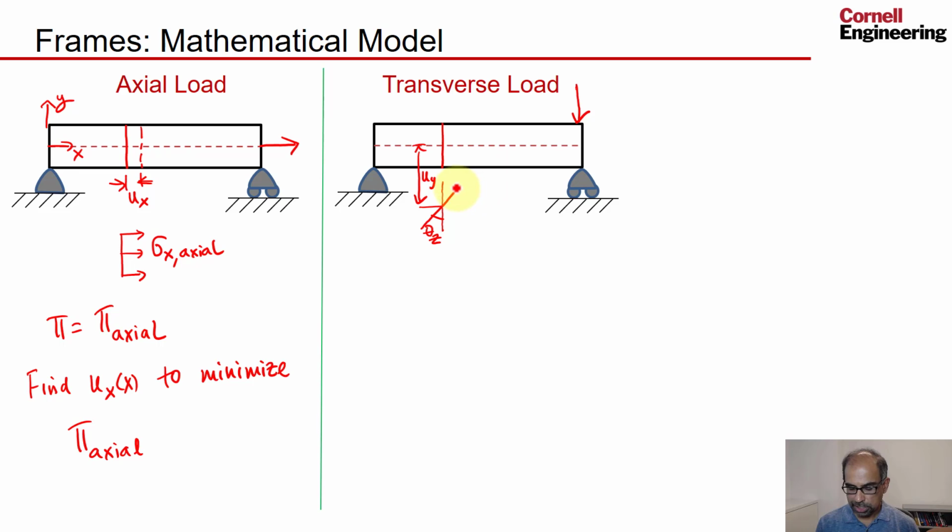And because of the rotation, it's the extremes that move the most, and they have the most strain and the stress. So if I look at the same cross section and draw the stress, at the pivot point over here, the stress is going to be 0, and it's going to be maximum tensile at the extreme because that's rotating the most, and then it's going to be maximum compressive at the bottom fiber.